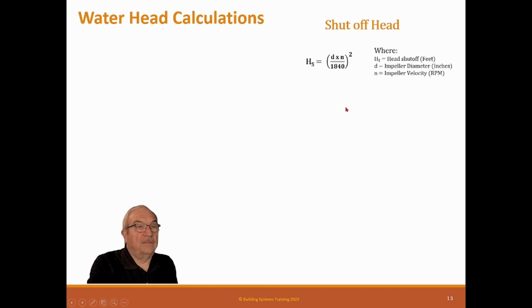Okay, shut-off head. Now this is something most people won't ever do, but the balance contractor, this is the way they find out what the impeller really is. No matter what's stamped on the pump, they do this test to make sure it has the correct impeller.